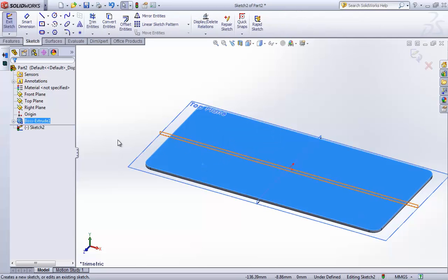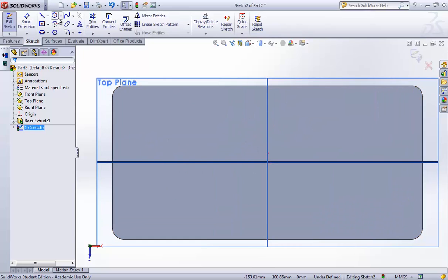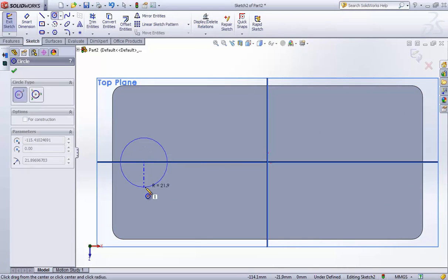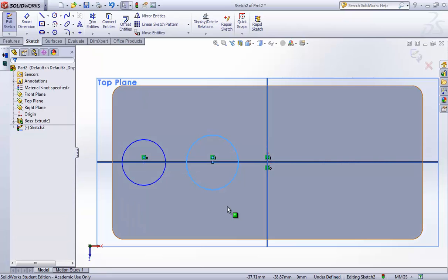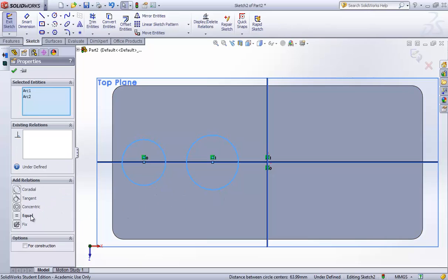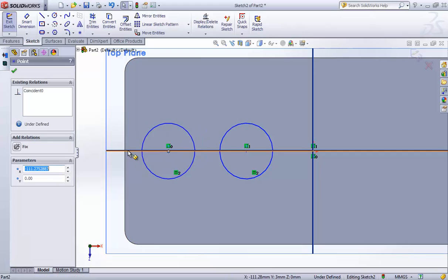I wonder if I can go and sketch on this level here, and now I'm producing those 4 circular cutouts. So if I were to draw maybe a couple of circles, what I want to make sure is, holding down Control, I select both these circles and make them equal in size. That has fixed it. I need to measure the distance, how far that is from the edge. I need to measure this distance here. So if you guys are doing this properly, you can stick a caliper here and measure that distance, etc.